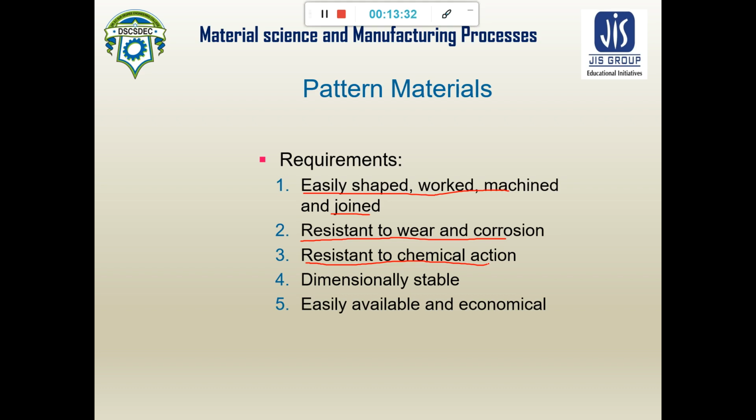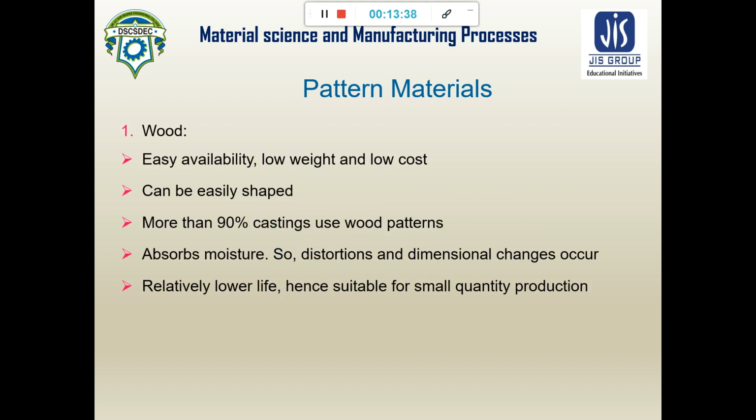The pattern material should be easily available, and it should be very economical. So we will now discuss the pattern materials. First, and very highly used, is wood. Wood is available very easily. It has low weight, low cost, and it can also be shaped very easily.